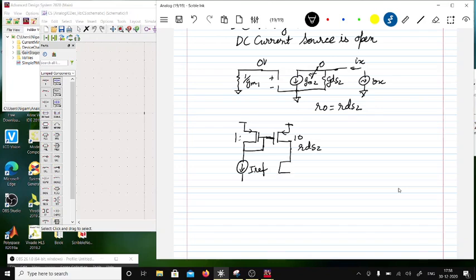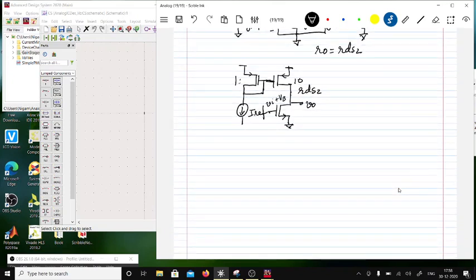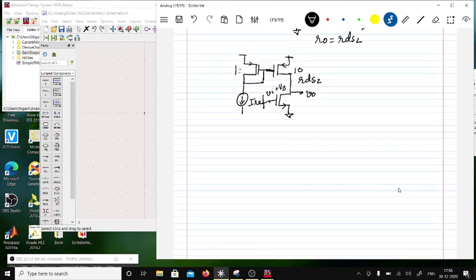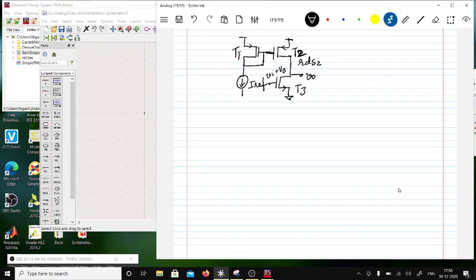And then there is going to be a gain stage here, okay, where here I will put VI on top of a certain bias, so this will be VB. So I'll put a VI on top of certain bias, and then I'm going to tap the output voltage over here, right? So now in this case, for the transistors, this is T1, this is T2, and this is T3. So for T3, let's say the output resistance is RDS3. So now let me draw a small signal model for this.